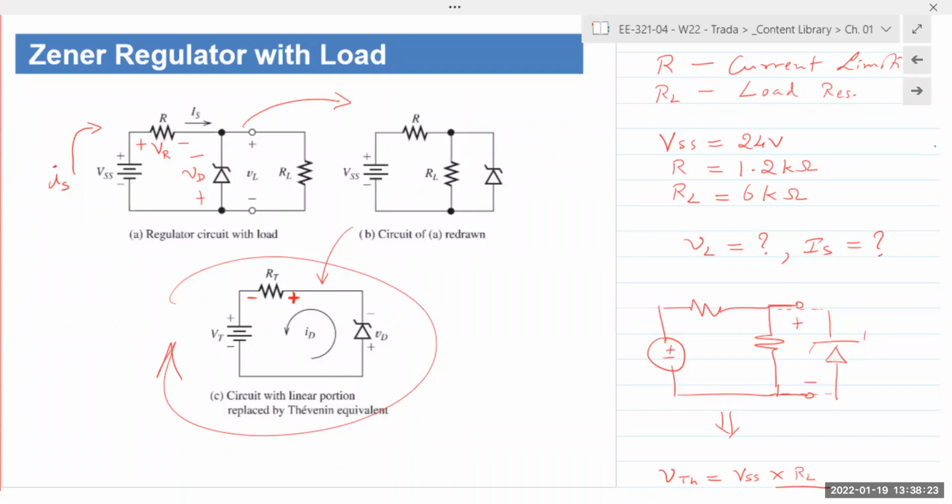Electrical power is always the product of voltage times the current, right? So if you have VZ and you have PZ max, you can calculate the maximum current that the Zener diode can handle without being damaged, right? If you exceed that, all of these electronic components get hot. Energy is transferred. A lot of the energy is released or dissipated as heat. And so it gets hot, right? So PZ max is basically the maximum it can handle. So the maximum it can handle is basically, let's say we are using 10 volts and 1 watt. How much current? It is equal to IV.